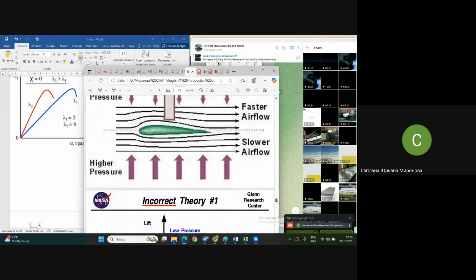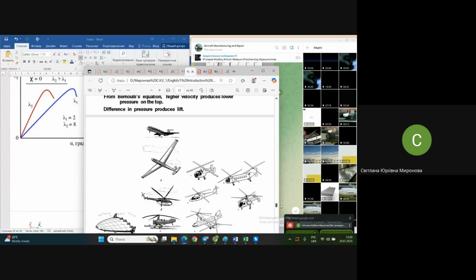Obviously, look, for instance here, the glider picture with a long and rather thin wing, not thin, but I mean the chord is not big. And here this relative span is much greater. And the military airplanes, maneuverable airplanes, they have the shortest relative span. They have rather short wings comparatively to gliders, for instance.